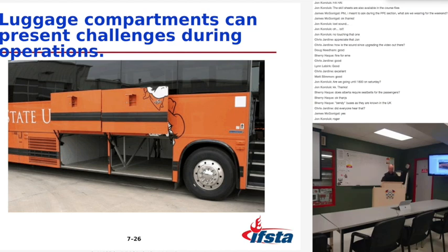But having said that, the large luggage compartments are near heavy fuel loading areas by the gas tanks. They may need to open doors on both sides when attacking with fire. Pike poles can pull or push cargo out of the storage area, and you get better ventilation that way anyway. Emptying can lessen overall fire damage and make extinguishment and overhaul easier.